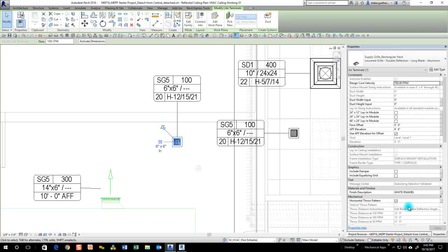So these auto-sizing families require design parameters. For the supply grill, essentially we're using design core velocity to auto-size the family. Anything grayed in is formula based, which means you can't edit it. So the 6" by 6", which is the value that shows up in the schedules and tags right here, you can't edit because that's where the formula resides. So this builds upon a system of calculated final values and overrides. In this case, anything with an input is an override.